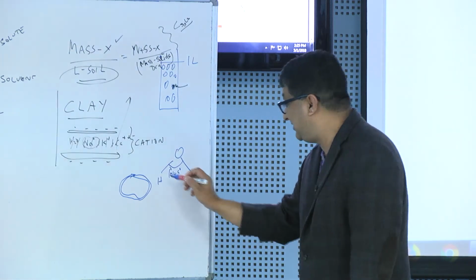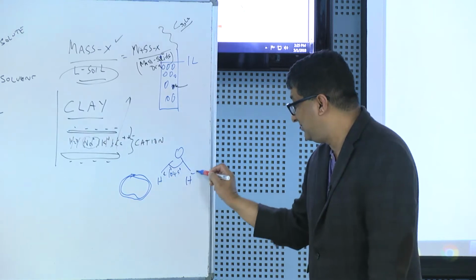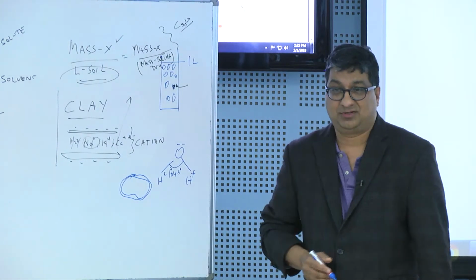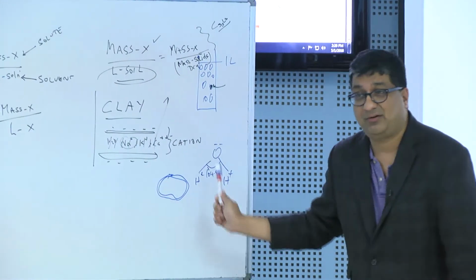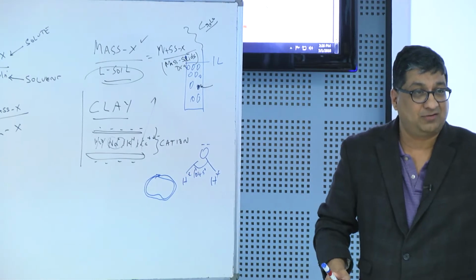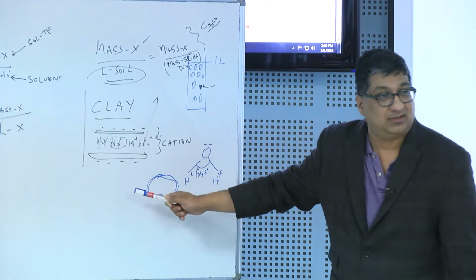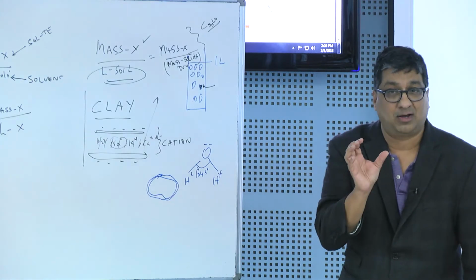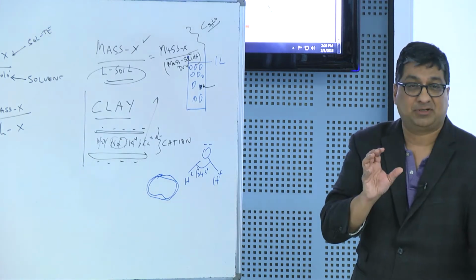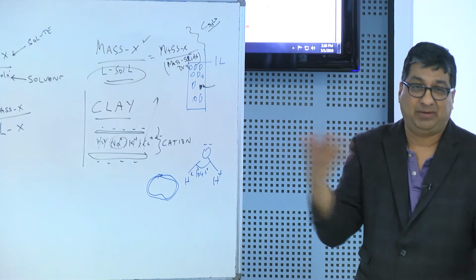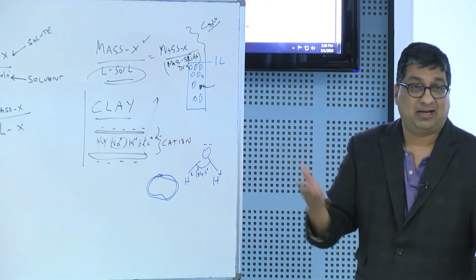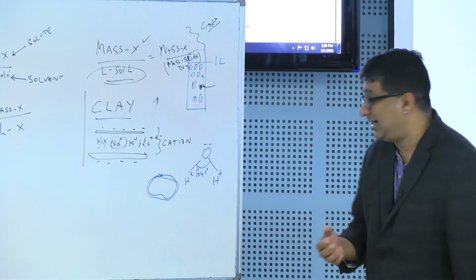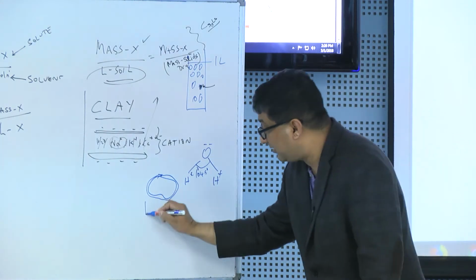And the reason we have that angle is because there are charges. Okay, so there's van der Waals forces, right? So what happens is, as I said, clays have some charge associated with them. So most of your mineral matrix will have some sort of a charge on the surface, and the water will attach to itself. So there is always a small coating of water on most minerals. The only exceptions would be if you have something that's very organic, like peat, or other very organic soils, which tend to be oil wetting. They're not water wet, but most of our systems tend to be what we call water wet systems.